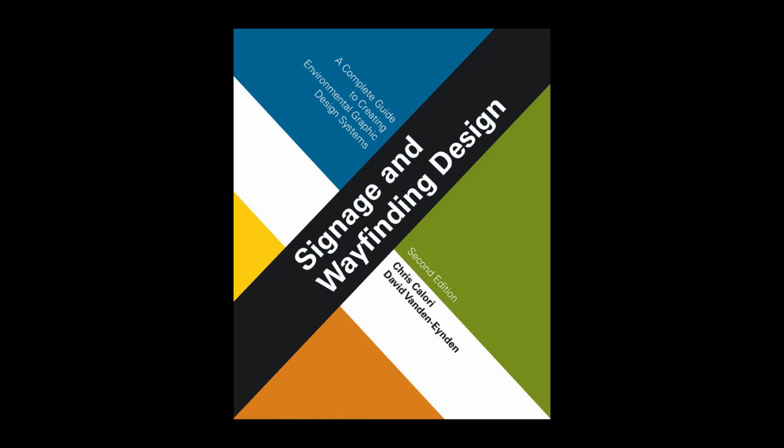Retro-reflective vinyl films are manufactured in a variety of grades and are typically used for traffic control and roadway directional signs at sites where there is little or no ambient lighting at night. See Figure 6.25.